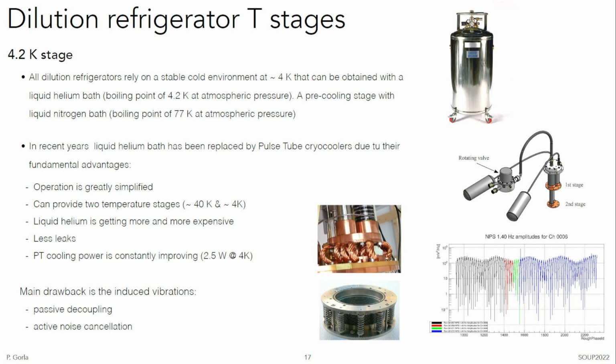This is a huge advantage in terms of lifetime and duty cycle because you don't need to do the helium bath refill, and it has much less problems like leaks, which are very common when you have a liquid helium bath, and you can have a very stable cooling power over time. Now the technology has improved so much that you can get some 2.5 watts at 4 Kelvin, which is quite a large cooling power. Of course, you have some drawbacks.